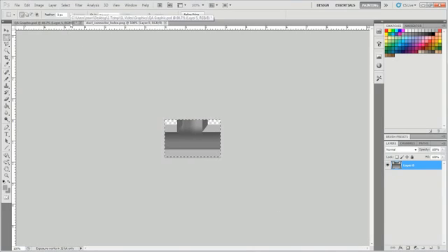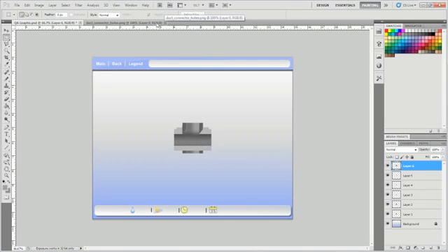After you paste the graphics into your PSD, you notice that each time you paste the symbol in, it created a new layer, and it's getting kind of messy. So we're going to clean this up by creating a folder to hold all of our ductwork assets. To do this, you click on the new folder icon in the layer window,